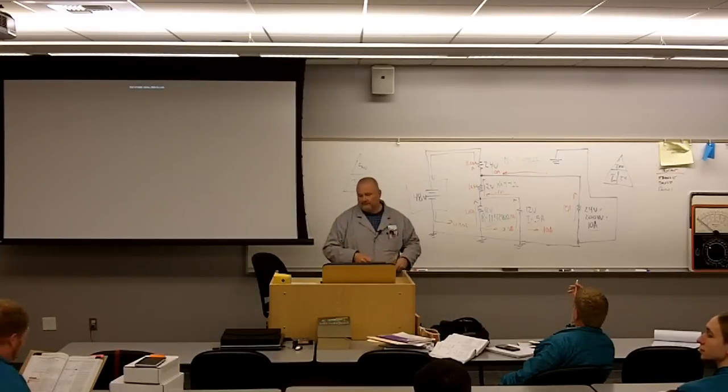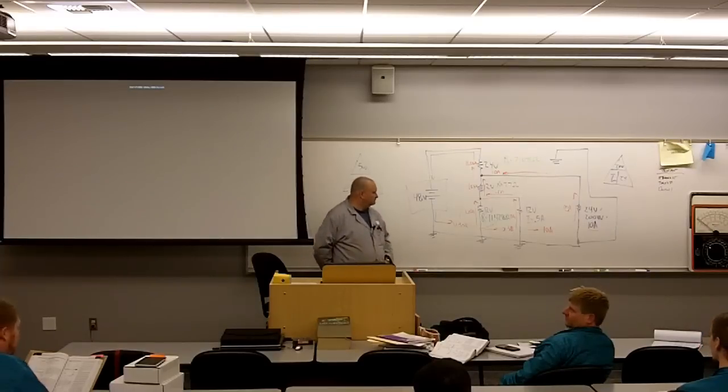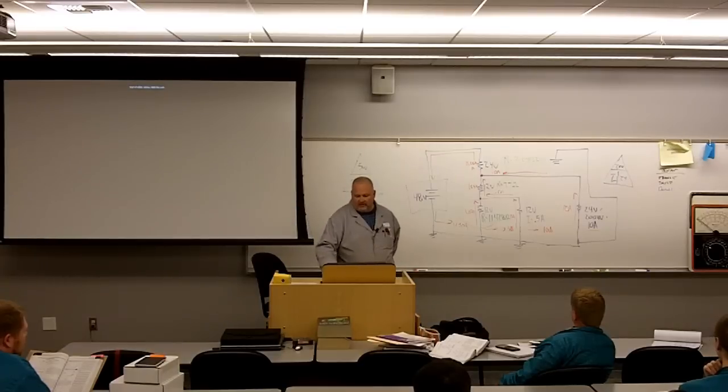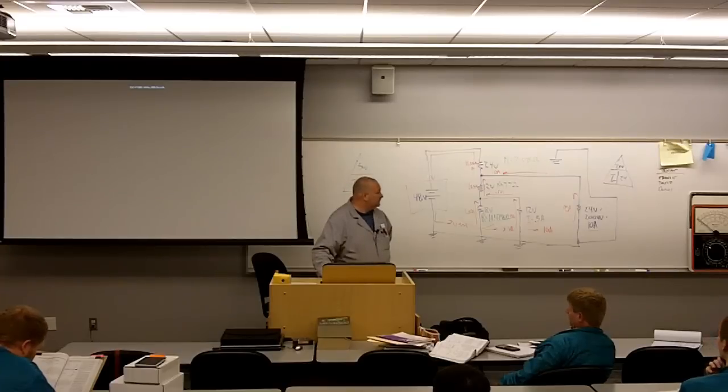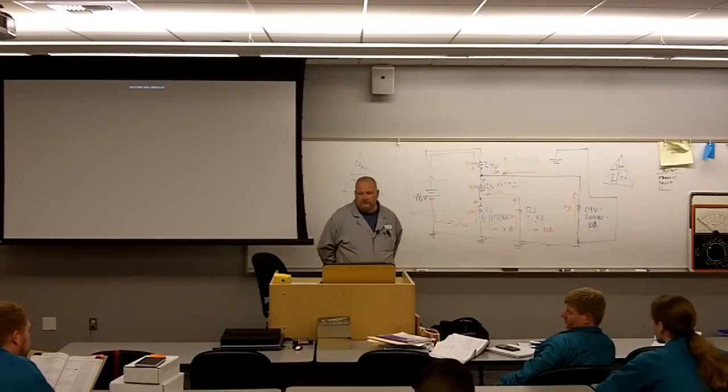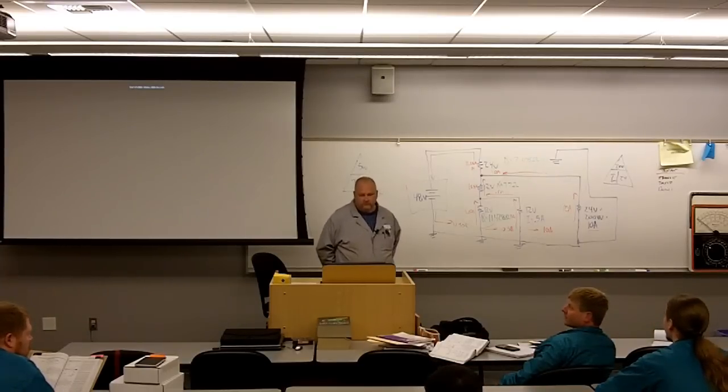Questions? With the beginning part where you need to figure out the meter current, take the total current, which is 10.5, and divide that by 1/10. Yep. Well, I'm not coming up with it. It comes up with 105, not 1.05. 10.5 divided by 10. Oh, divided by 10. 1/10 is 10, right? Make sense? 10.5 gives 1.05. You can multiply it by 0.1, you get the same answer. 10% of 100.